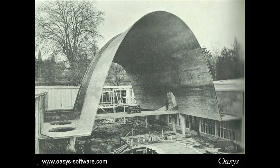Now, again, if you get the geometry right, these compression-only structures can be amazingly elegant. And here's an example from 1939, Robert Maillart and his concrete shell for the cement hall in the National Exhibition in Zurich. Scale, well, you can see that there's a man on the bridge, so I'm not sure of the exact dimensions, but it looked to be about 20 meters high, and thickness must be about 50 to 100 millimeters. I'm not sure, not a lot.